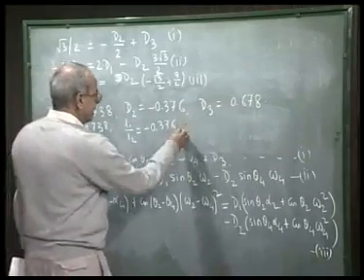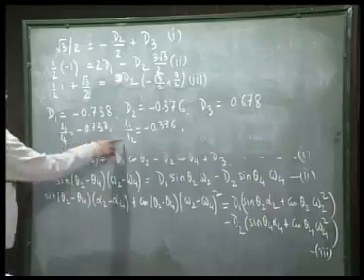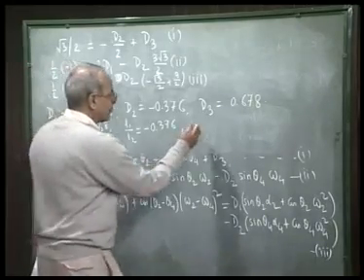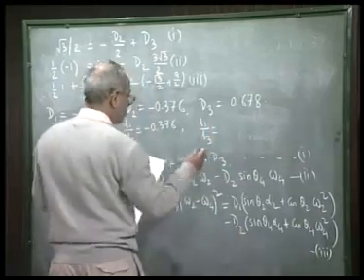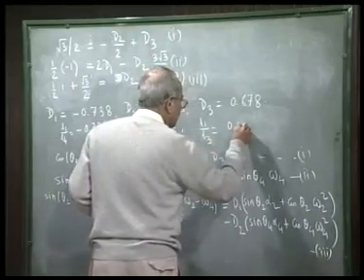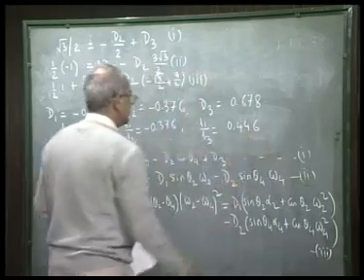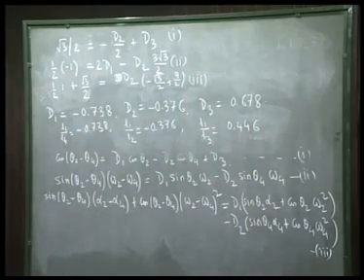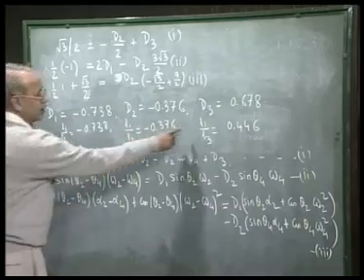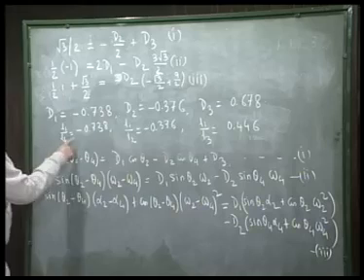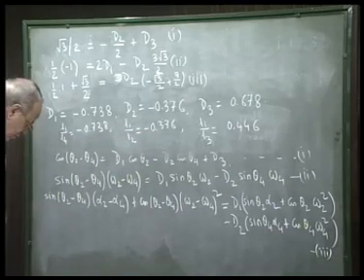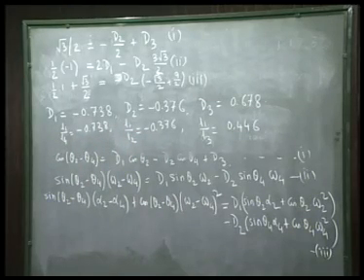and from d3, if I substitute these values of L4 and L2 in terms of L1, we can find out L1 by L3, which turns out to be equal to 0.446. So, we get all the three link length ratios, and as we said, L1, L3 are always positive. For this particular problem, L2 and L4 are turning out to be negative. So, if we choose the length L1, we can solve for L2, L4 and L3.